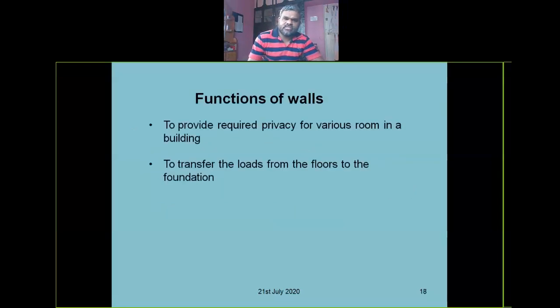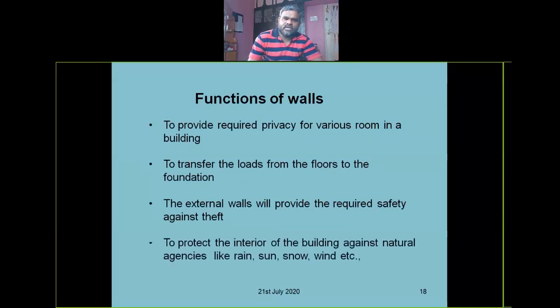Functions of walls: to provide the required privacy for various rooms in a building, to transfer the loads from floors to the foundation. The external walls provide the required safety against theft. Generally external walls are thicker than interior walls, right? To protect the interior of the building against natural agencies like rain, sun, wind, or weathering agencies, we require walls,